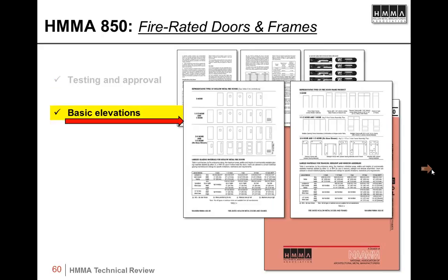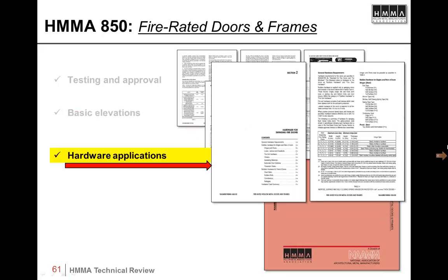Basic elevations are covered, showing the size limitations, showing the designs, along with your frame profiles and limitations for hourly ratings, hardware applications, etc. The hardware applications are spelled out. These are all in accordance, both the door frame design and hardware applications, with current NFPA pamphlet 80 requirements.